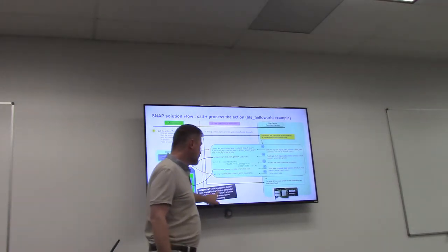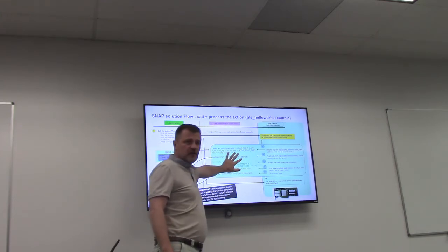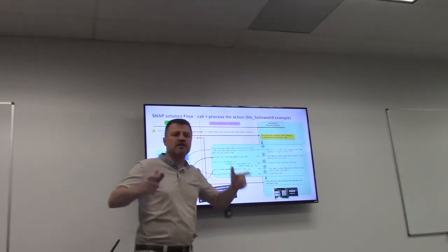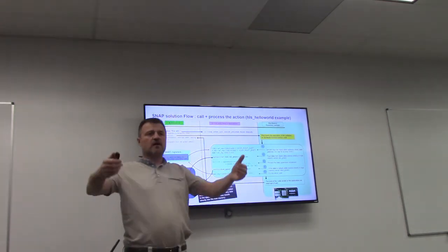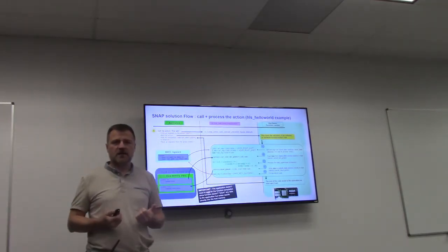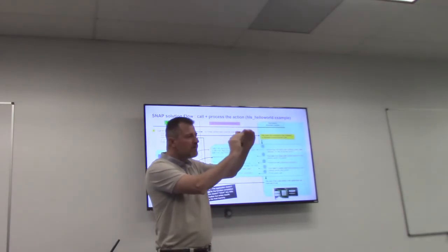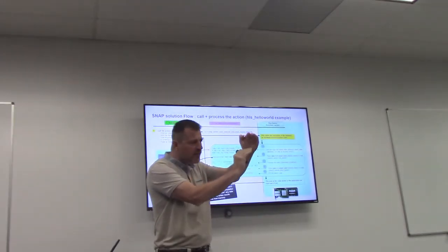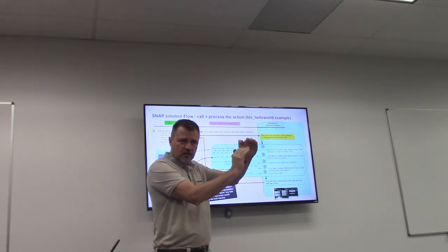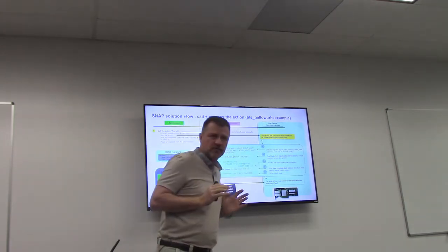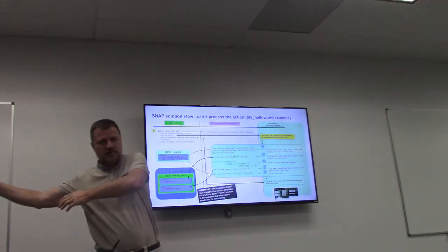Important thing that we have written here: by the time the FPGA is computing, you don't need to wait, that's the goal. We are offloading the activity. So you give a very small bunch of instructions, what are the addresses, what I expect from you, where data is located. You give the job to the FPGA, and then you can do something else.